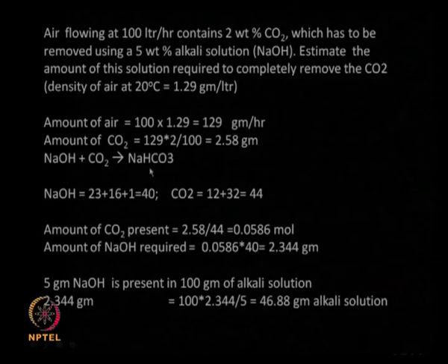So carbon dioxide will quickly go into solution but it will not react, so there is going to be a build up of carbon dioxide inside the liquid phase. Both situations can happen in a non ideal condition, but here we are assuming an ideal situation, and in an ideal situation we assume that as soon as the carbon dioxide comes in contact with the alkali, it quickly reacts and forms sodium bicarbonate.